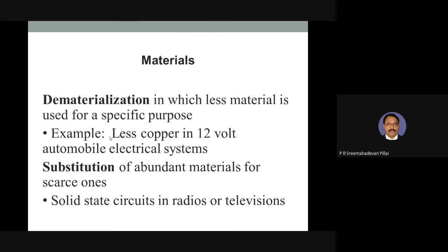For example, if you have lesser conducting equipment, you don't have to use heavy conducting materials. You can save the material. Say your electrical appliance is only, say, 2 ampere. So you don't need a 15 ampere switch, and you don't need 15 ampere wiring. You can get sufficed with 5 ampere wiring, which we normally give for a single phase. So a 5 ampere wiring will be sufficient to take all the load coming in. Of course, if you expect more load, you can go for that. So wasting the material can be avoided as much as possible.